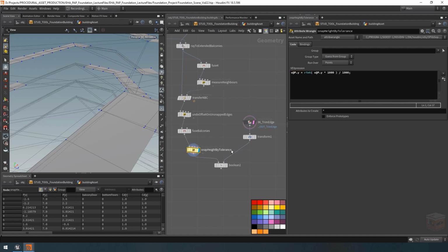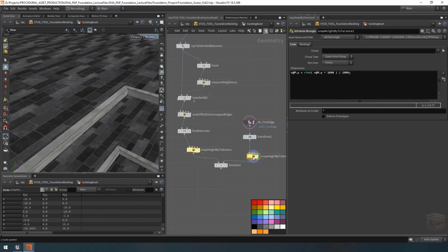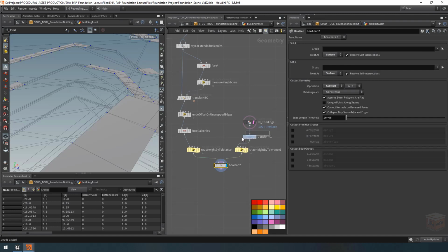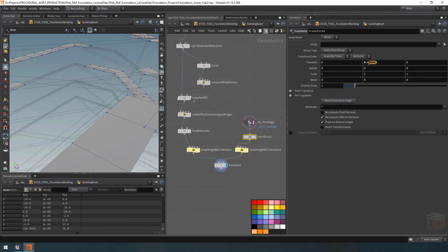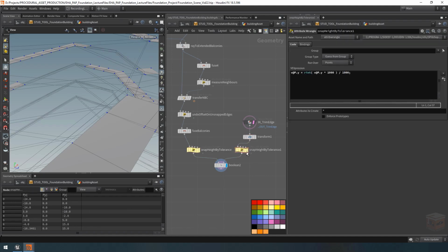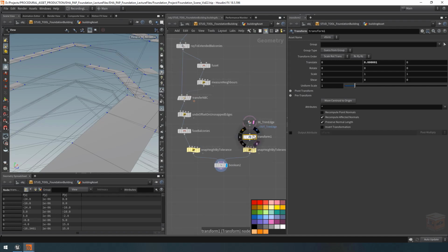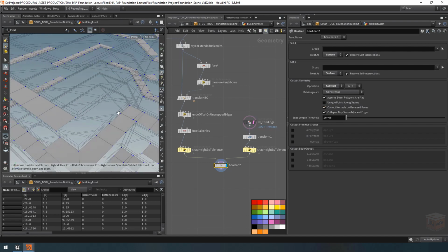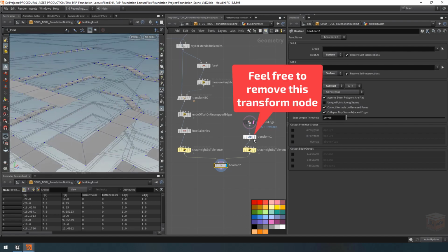If we do that for both these meshes, then now they should be lined up. So if we have a very, very small difference in height, it will be corrected by these snap nodes right there. That's just in case this goes wrong. Like I said, Boolean nodes are very precise. They have a very high precision level. And if your meshes even differ slightly, you could get slivers, you could get weird issues. I want to avoid that. So let's set it up like this.